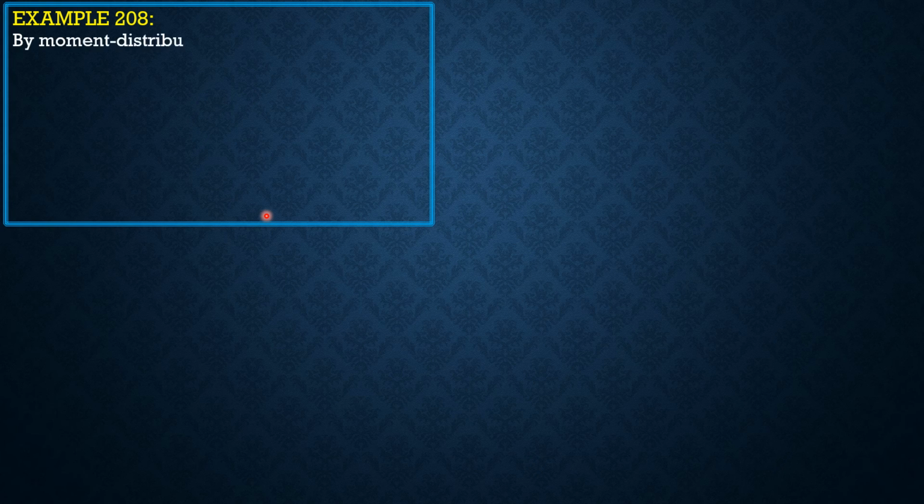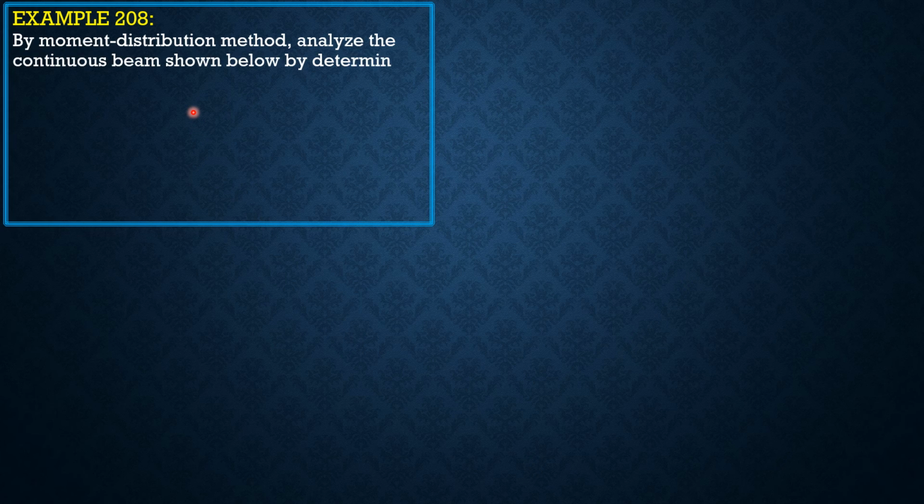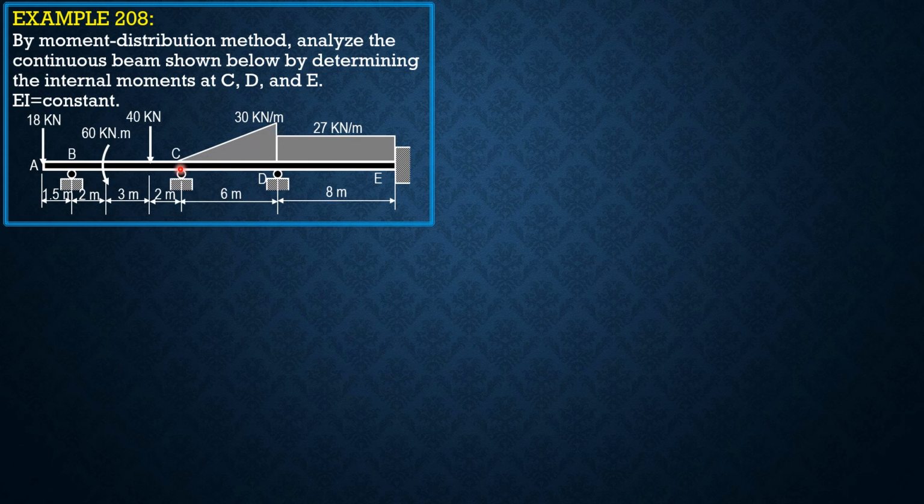So this was solved by three moment equations. Let's verify the answers by the moment distribution method. Analyze the continuous beam shown by determining the end moments at C, D, and E. EI is constant. The loadings are basic, so you just need to be familiar with the formulas.